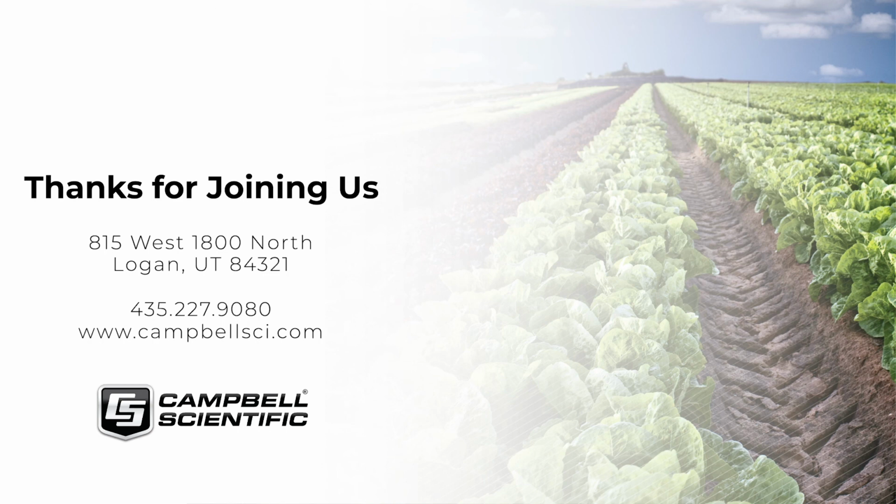The deeper you get into the soil, the less these things are even a factor, but it's up near the surface where you need to be at least aware of those effects. And I'm going to throw in one other source of uncertainty, which is that we're taking a point measurement and soil is not homogeneous. So a very short distance away, you could be at a different water content.